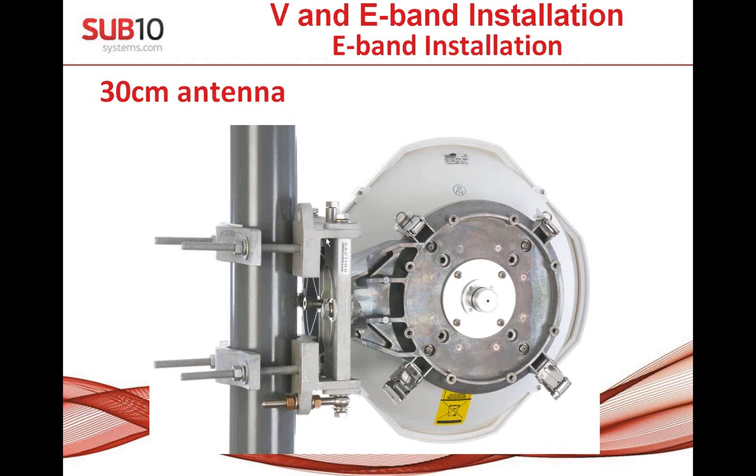And same if you look at the screws which are here, they are metal and they are going into the aluminum type of pieces. It's good to use some lubricant on this one, because later on if you need to open it, from time to time it's not so easy. If you have metal and aluminum going together, they can make a very fixed connection.